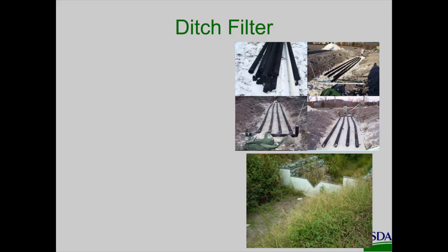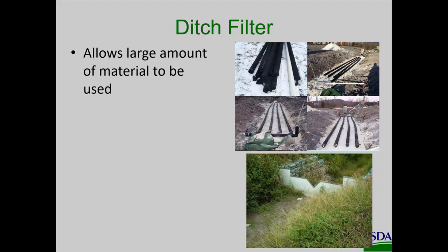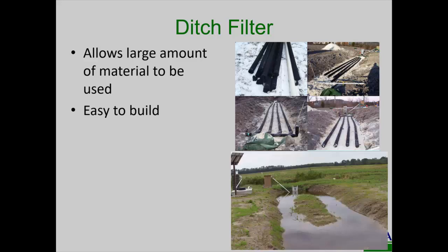Ditch filters, this is something we built a lot of on the eastern shore of Maryland, treating surface water. These are nice because the ditch acts like the box to retain the PSM filter material all by itself. So it allows you to use a very large mass of PSM. You start out with a bed of drainage pipe, and then you backfill it with your PSM. You can use a flow control structure to maintain a head of water on top of it.